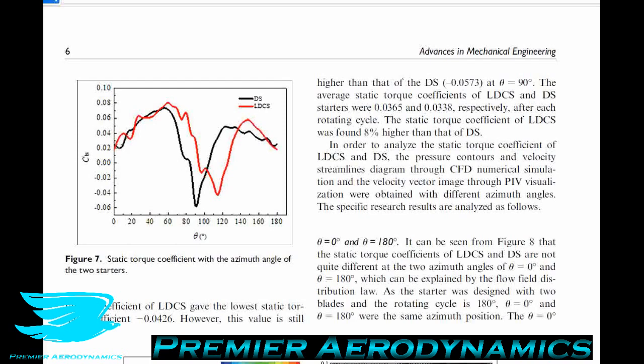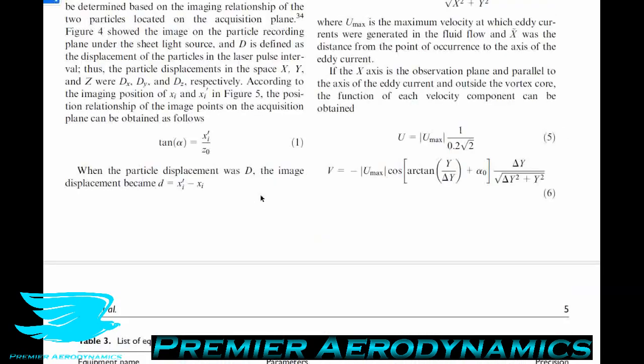Interestingly, both lines follow a similar trend, but there is definitely an offset. We can see that for the red line, the minimum occurs at about 120 degrees, whereas for the black line, which is the drag producing blade only, the minimum is about 80 to 90 degrees. This offset is due to the addition of these airfoil profiles on the blade tips that alter the overall force generated. One thing to note is that at 0 degrees, when the blades are on either side of the axis, this is where we have this exact setup here.